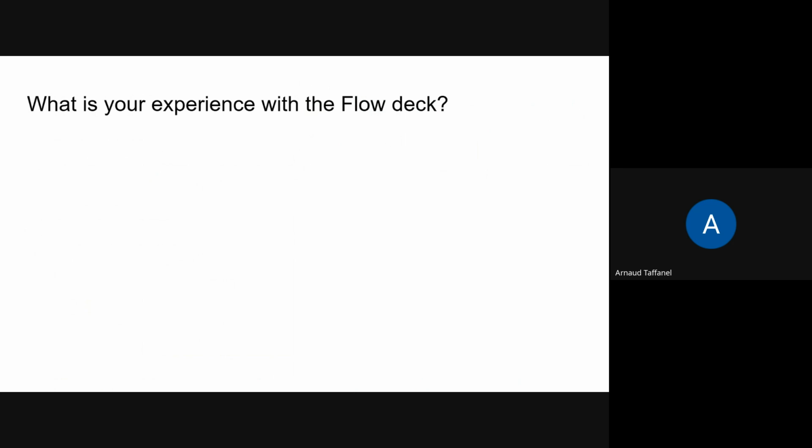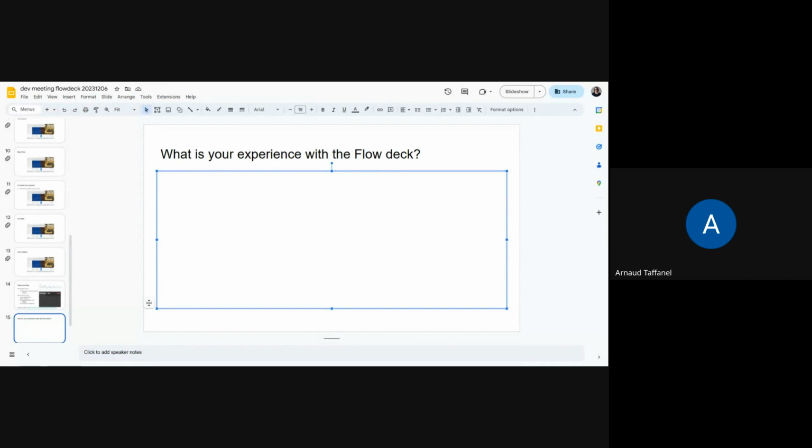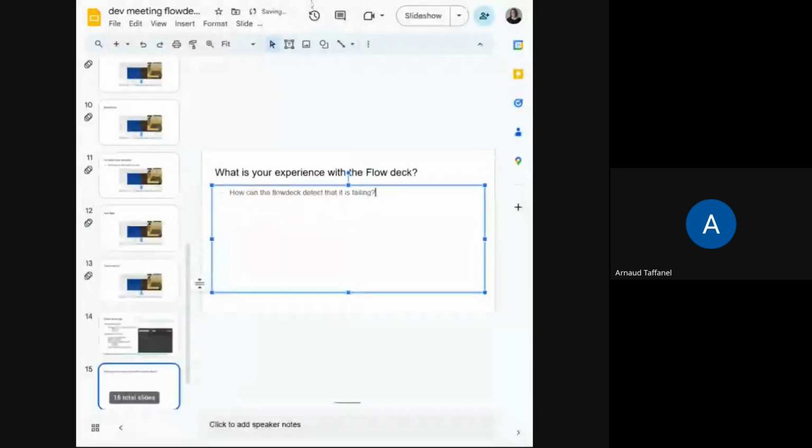Just at a low level, I think it might be interesting to think about what the flow sensor is. It's basically a high-speed camera with automatic gain control on the images, which can actually cause problems. It does a cross correlation between two consecutive images and tries to give you the best estimate for x and y of how these two images have moved. This can fail in multiple ways, I guess. But most likely, you're getting random noise from this algorithm if the sensor gets confused and the data are not good enough.